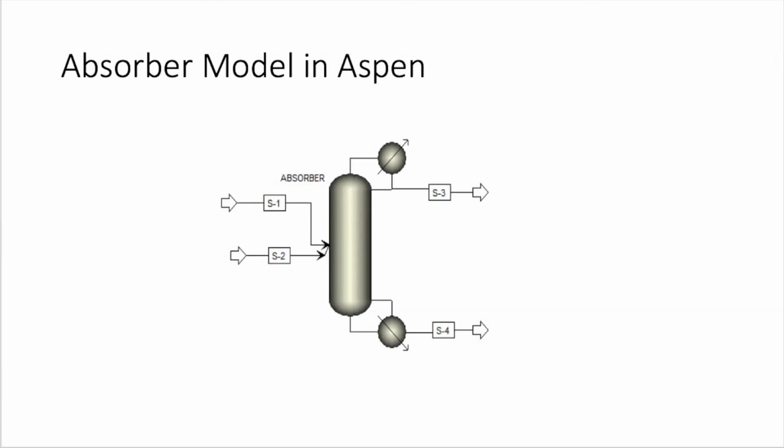Aspen Plus software was used to model the absorption column system used in this lab. Aspen Plus does not have a unit op for absorbers, so instead a RadFrac distillation column was used. The column was designed to have a 24-inch area packed with ceramic Raschig rings with a length and width of 0.375 inches. The column was also designed with a 4-inch inner diameter, operating pressure of 1 atm, and a pressure drop of 0.001 atm.